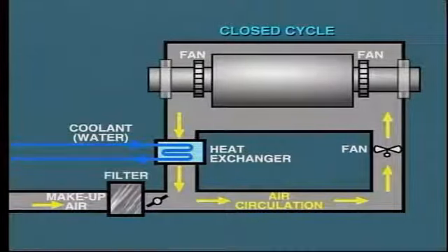Filters are provided on the make-up air inlet from atmosphere. In other designs, the shaft-driven fans are made larger to avoid the need for a separate air circulation fan. With this arrangement, make-up air is drawn in through the generator housing by these fans.